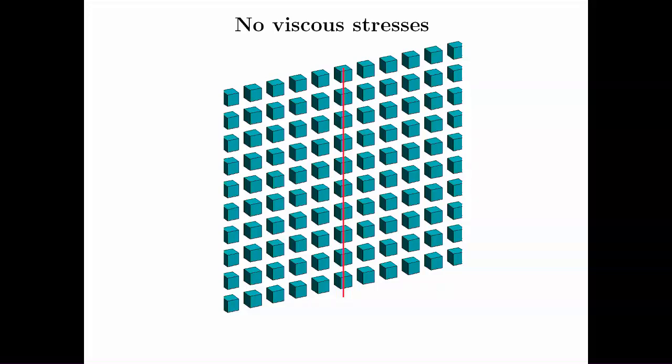But before that, does everyone know what viscosity does to the fluid, or what the viscous terms do to the fluid? Anybody want to guess? Friction, yes. Yep, friction, because you have a no-slip condition. Anything? Boundary layer. Yep, exactly. So when you have viscous stresses, you're going to form a boundary layer because of the no-slip condition at the wall.